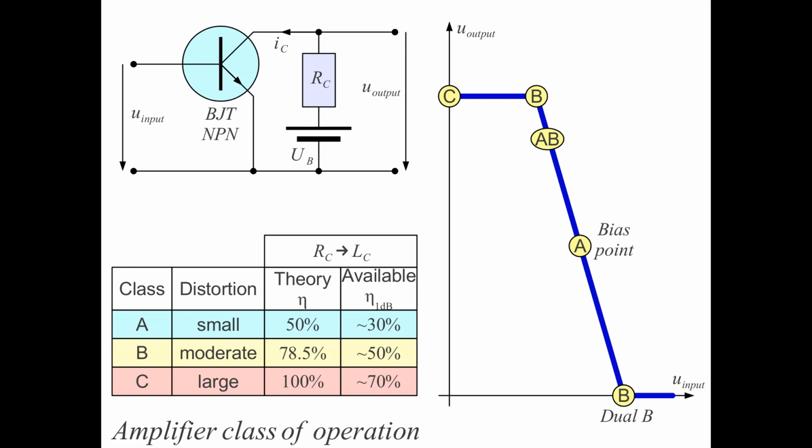in the amplifier. Most devices, say vacuum tubes, bipolar transistors, field effect transistors, allow the adjusting of the bias point. There are also some active devices that do not allow almost any adjustment of the bias point, like traveling wave tubes, klystrons, or lasers in optics.